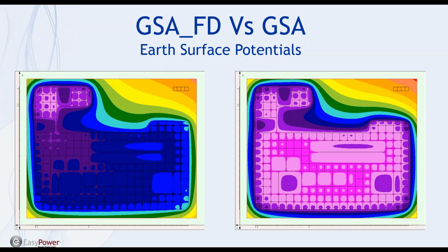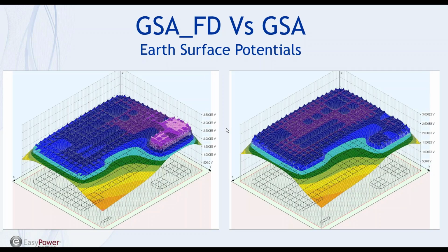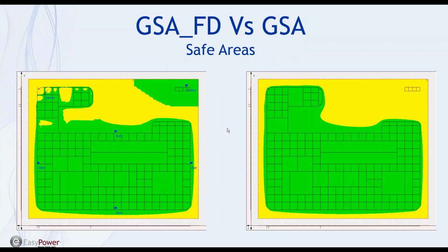because by considering this, we can find out, for example, as you can see also in this slide and this other slide, that the earthing system is not safe, unlike what the equipotential condition shows. In the case that we have just analyzed in this webinar, the same calculation with the equipotential condition gives a result telling us that the earthing system is safe.